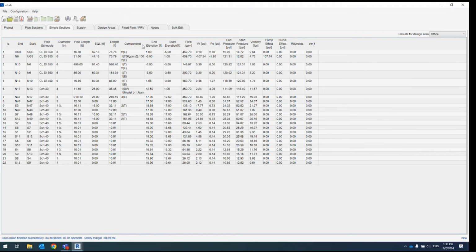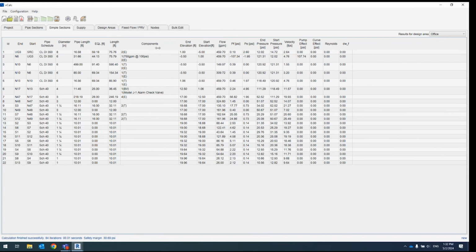If you're kind of following the components column, you can see that some of it's a bit more amalgamated here. So this is going to be a lot closer to your NFPA 13 pathing. So it's going to condense down all your typical sections for the current design area, and I've added them all up into one. So this is obviously only all your flowing pipes. And this can be a pretty handy way of maybe interpreting the results a little bit easier than trying to go through that full pipe sections tab.